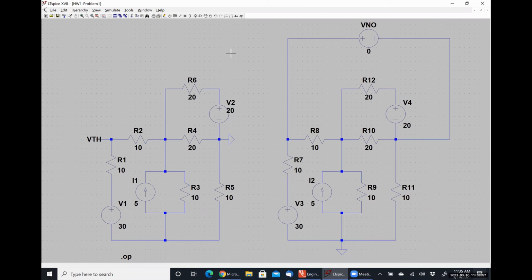On the right-hand side here, what I have done is placed a voltage source that has a value of 0 volts to represent my short circuit. The reason I have to do that is because if we mouse over a node, which is any wire, it's only going to give us the voltage. It doesn't give us current. If we mouse over a component, it tells us the amount of current that flows through that particular component. In our DC operating point analysis, when we make it spit out numbers, that's how it does things as well. It tells you I, open parentheses, and the component label, saying that the current that flows through this component has this value. So I can't simply draw a wire here, or there's no component for me to take the current flowing through. So I threw in a 0 volt voltage source, which is the exact same thing as a short circuit, and it gave it to me.